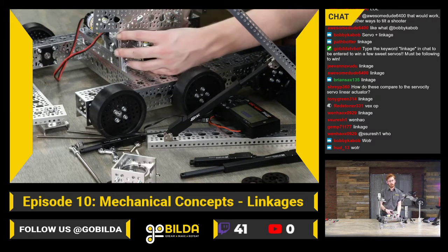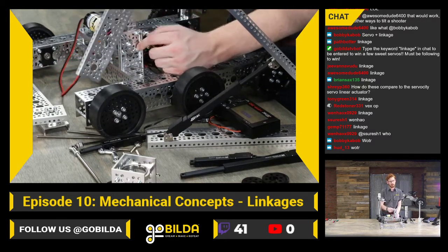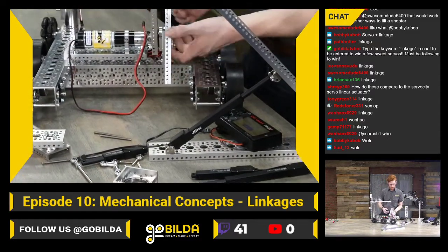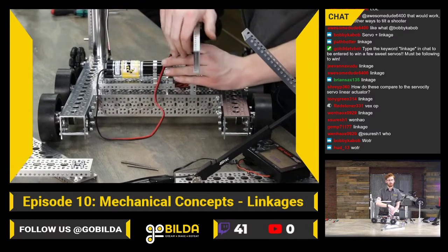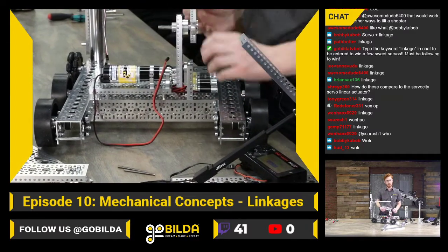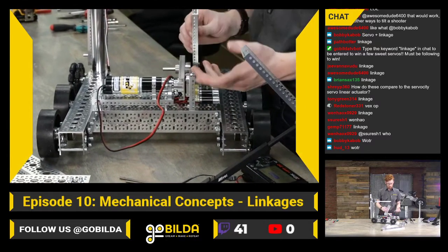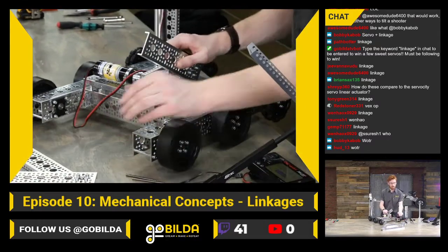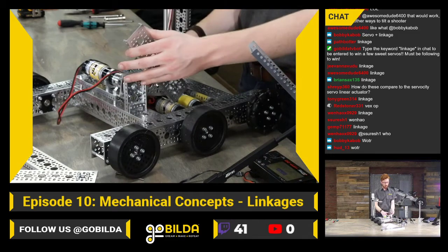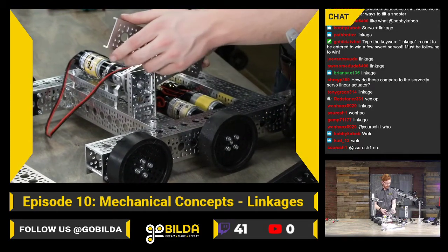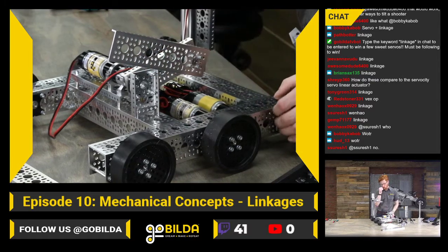This is using another 32mm bearing to support the output shaft of this motor, so you can be pretty solid, and you can put a ton of weight on this with all of the bearing support on there. In this case, this would be a great linkage style to use to move something vertically. You could, say, fix this to a linear slide, and as you rotated this, you could push that slide up or down. This joint is a dual pattern pillow block.